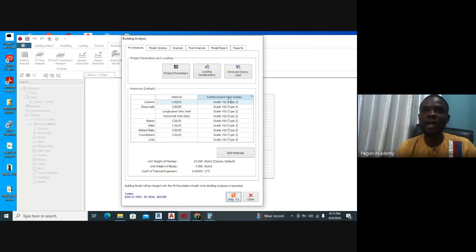For 1 bag of cement, you might use 4 head-pans of sand and 7 head-pans of granite, or 5 head-pans of sand and 8 head-pans of granite. Now, what you are simply doing is determining the grade of concrete based on the concrete mixture. If you use 3 head-pans of sand and 5 head-pans of granite for 1 bag of cement, it is going to give you a different concrete grade compared to other mixtures. All right. So that is just a layman explanation.